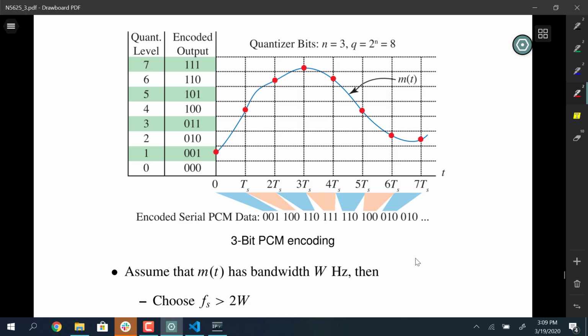This is depicted as a unipolar type converter. When I say unipolar, I mean amplitude values would be all positive. And that's actually a pretty common PCM encoding that you find in a microcontroller. Oftentimes you have a unipolar conversion done there. Most often, the real motivation for that would be you only have a single bias supply on the microcontroller, say 3.3 volts, so you can encode analog inputs over a dynamic range that goes, say, from 0 almost to 3.3, the supply rail.